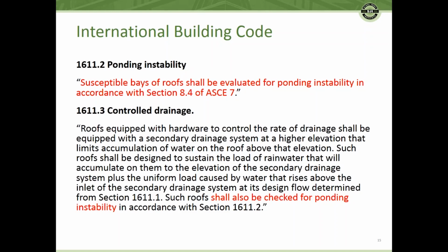And the big problem there was if the structural engineer didn't know that's what was going on, you may have 6 inches or more of water on the roof, and certainly it was a major load. But like I say, I don't know how much of that's going on today, but you need to make sure.